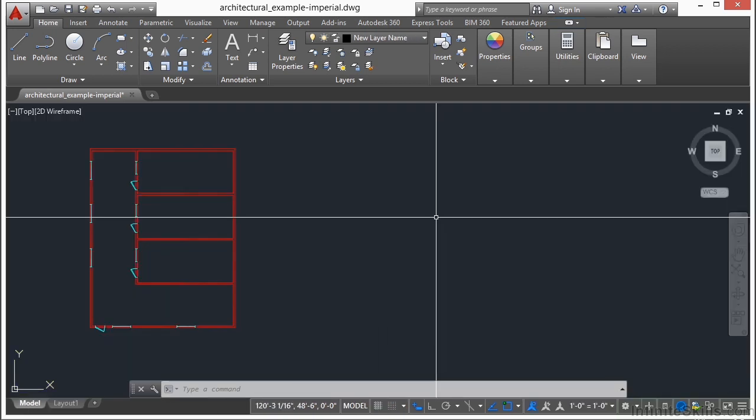So you can isolate objects or hide objects by viewport through those viewport-specific settings. The nice thing about being able to do that is that I can have one set of line work, one model, but I may need to display it differently on multiple drawings. Well, this allows me to do that without having to draw new layers for specific reasons. I can use the same ones that have the information on them already. I can just choose to not display it by freezing them in that specific viewport.